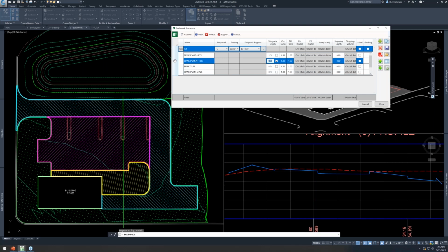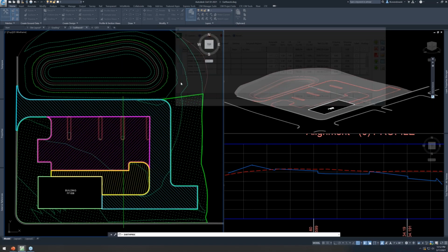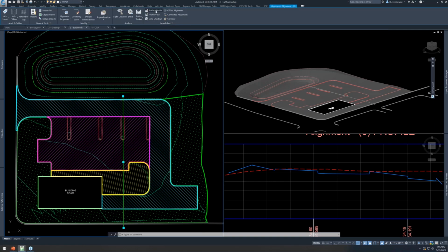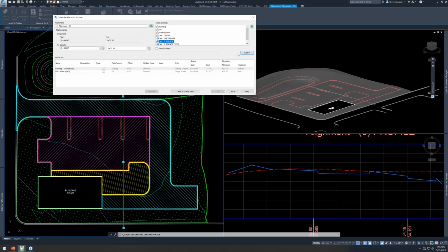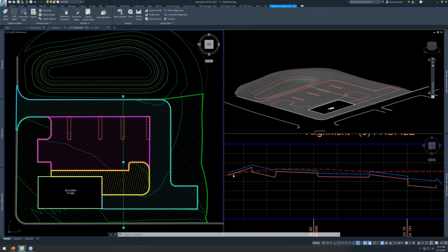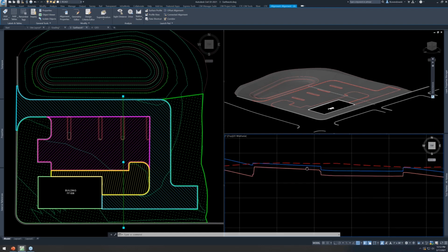If I change these, for example, say that should be 0.67 feet, 8 inches instead. I click the override, I click run again, and it recalculates, and we'll get different cuts and fills because my hold down varies now. Now, what is this creating? This is creating a number of things behind the scenes, but most importantly, it's creating a subgrade surface for us. Let me add that right into my profile view. Okay. So the left side here corresponds to the bottom of the alignment here. So you can see there's my turf area, 1/2 foot hold down, 1.5 foot hold down, 8-inch hold down, okay?